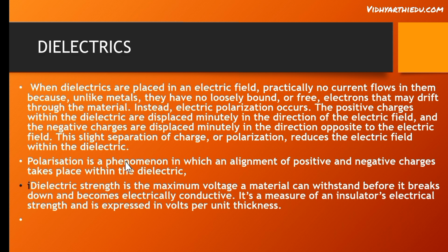See, what is meant by polarization? Polarization is a phenomenon in which an alignment of positive and negative charges takes place within the dielectric. Whenever some voltage is applied to the dielectrics, the positive charges will move towards the applied high potential and negative charges will move towards the applied negative potential.